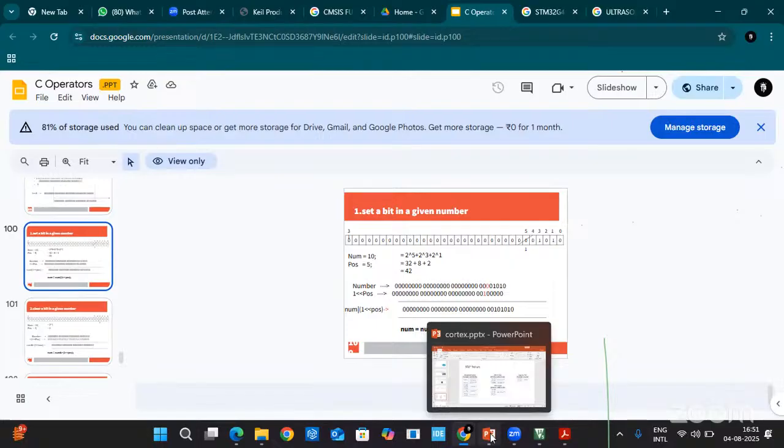Another important point: with a processor we can add extra storage. A controller has a single purpose only; we cannot add storage. For a processor, CPU, RAM, ROM, timers, peripherals are all separate, but for a controller everything is inbuilt: peripherals, ports, RAM, ROM, CPU, everything inbuilt only. Okay.